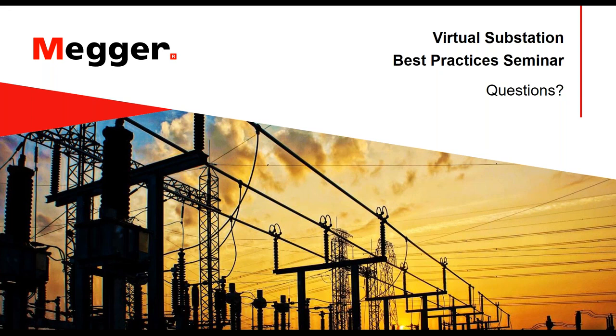And Megger has a couple of those instruments like the MWA, which is a Megger winding analyzer, and then Megger also has a TRAX unit, which is a multifunctional test set, and both of them are capable of performing winding resistance and TTR from one single test box.